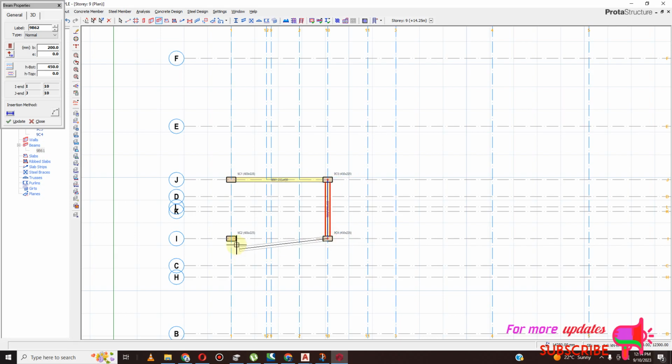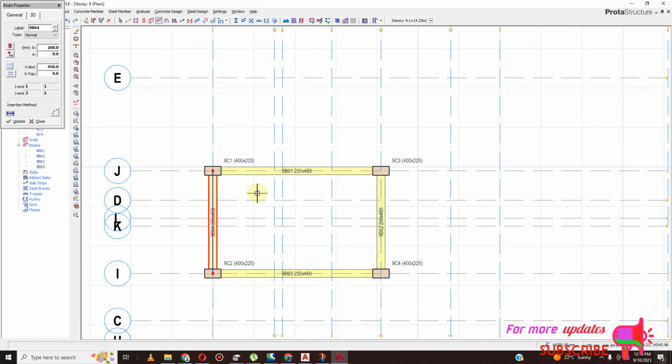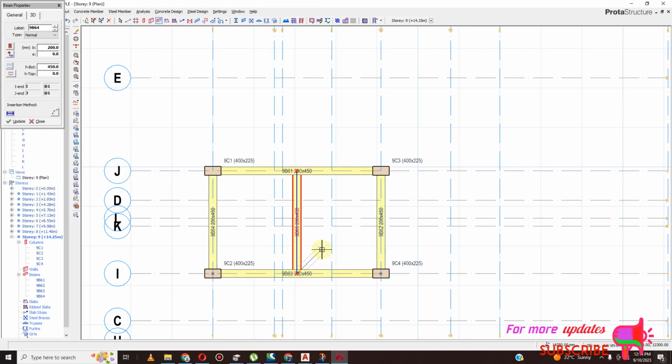And remember, water tank is very critical, so for me I think this distance might be a little bit too big, so I need to insert another beam right in the center. So I will insert another slab for the water tank. Now my slab for the water tank should be 175. And then the loadings for self weight.